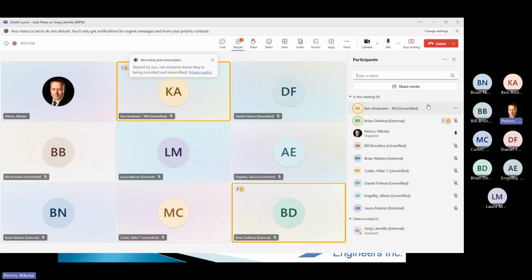But one thing that, if you read on the Northridge earthquake, contributed a lot to the failures we saw in moment frame buildings was the practice of having relatively non-redundant moment frame systems. They would take this big building and put one big honking moment frame on each of the 4 sides and call it good, because that was less expensive than having more spread out moment frames, where you incorporate 2 bays or have 2 on each side of the building. And I don't know that we did that much up here.